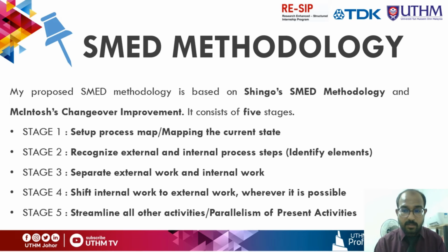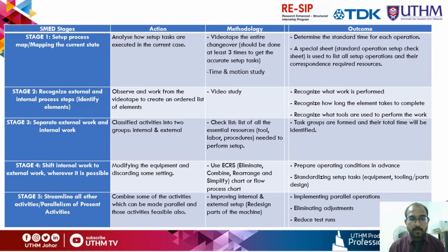My methodology is based on the literature review that I did. It is based on Shingo's SMED methodology and Macintosh's changeover improvement. It consists of 5 stages. Stage 1 is the setup process map and the mapping of the current state, which is already done in this FYP1. The action is to analyze how setup tasks are executed in the current machine. The method is to videotape the entire changeover process on the terminal welding machine, so the outcome is that we can determine the standard time for each activity in the current changeover.